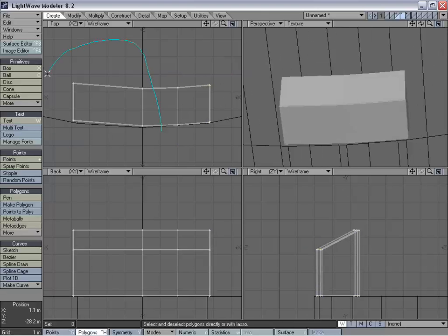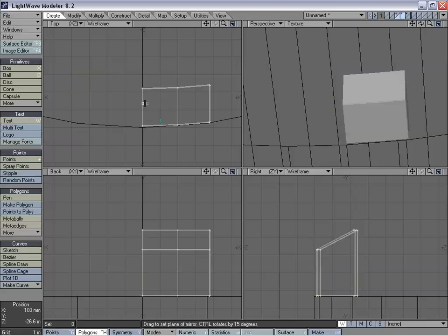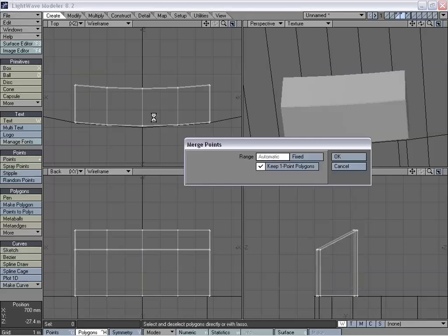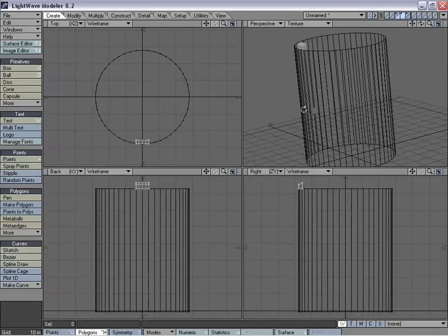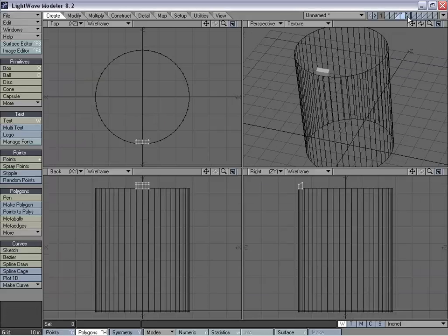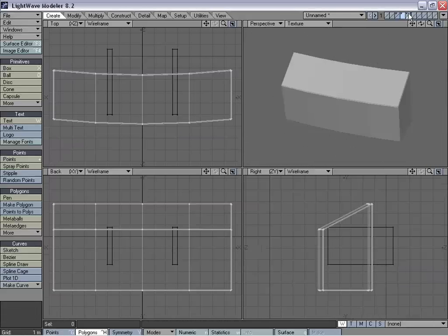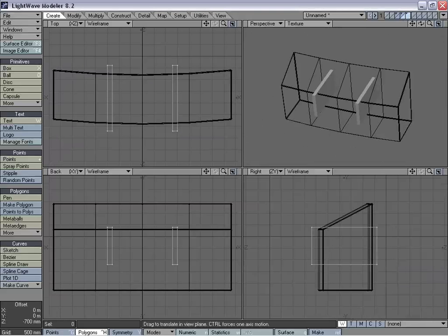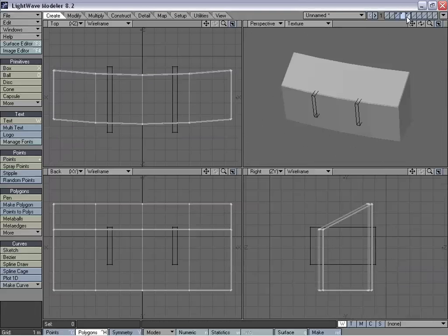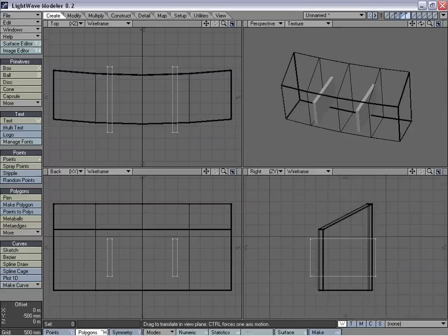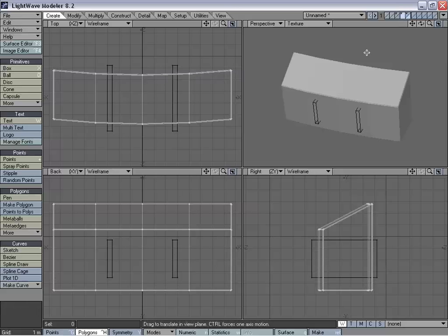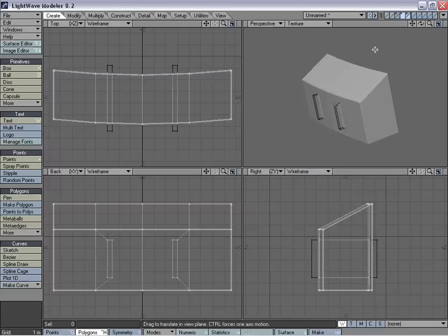And then we can delete this side and mirror it over so it's exact. And now center our arrow loops, and actually I need to pull them down just a little. And now we can do our Boolean subtract.